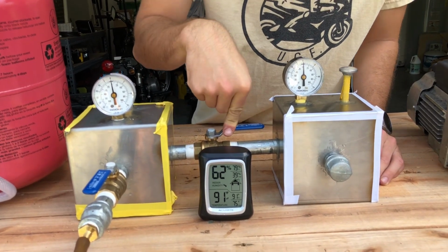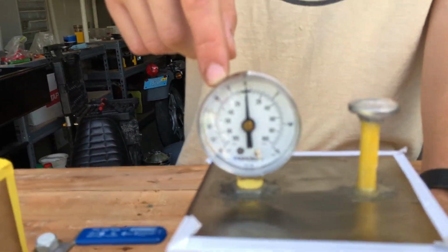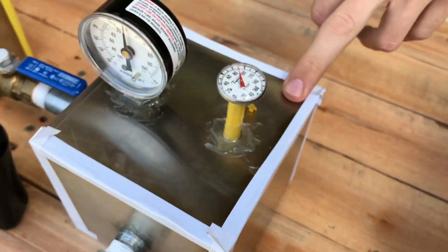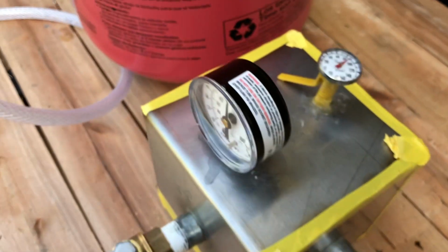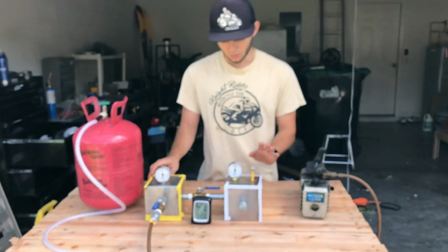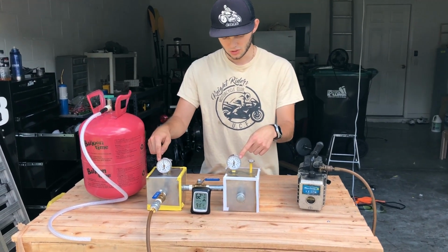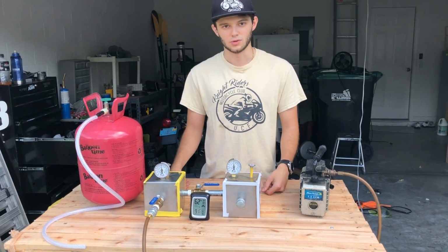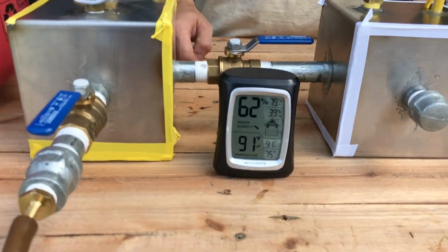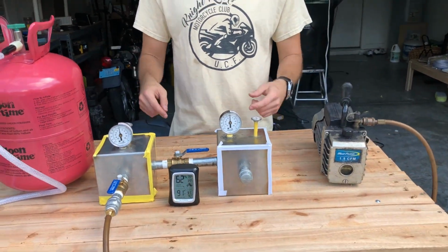manually actuated valves, and then we have our pressure gauge to show our vacuum and to show the pressure differential, and we have temperature probes on top as well to see the temperature in each of the chambers. So that'll show us when we flip one of the switches and have the vacuum and the helium interact, you can see the change in pressure in each of the chambers and the change in temperature in each one of the chambers. And we also have the ambient temperature of the surroundings. So that'll show us heat flow in and out.